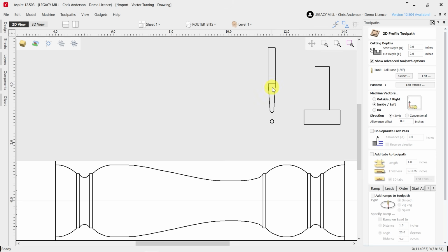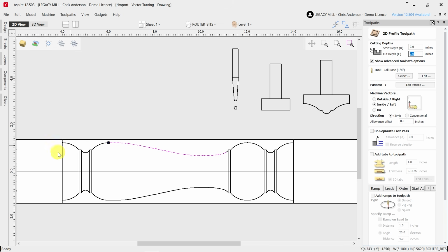And so I like to have my cut depth greater than the profile height of the tool that I'm going to be using. That makes it so that the Vectric software doesn't accidentally shift my cutter the wrong distance away from the original contour line. Okay, so that's why I have a big cut depth here of 2 inches, and it's going to do it all in one pass. That again, it's not going to actually do that for cutting from the side. This is what we're simulating. We're simulating this in this software as if it's cutting from the side of this contour effect, just a flat stock component.